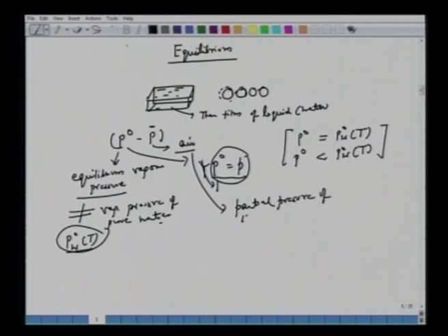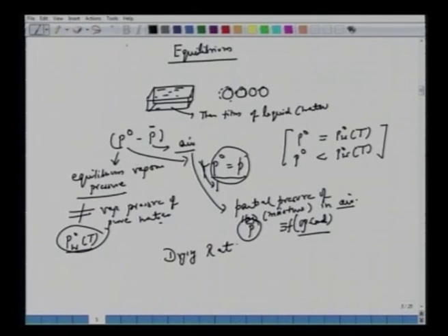Partial pressure of moisture in air or atmosphere. So this P bar, that means it's dependent upon what operating conditions we choose. It's not something which is fixed. So different partial pressure in atmosphere, different quality of air will give different drying rate. So we are slowly getting into this design business, drying rate. So it's characteristics of a drying of a solid here. All right, so that's the driving force we are talking about. Okay, that's one thing.